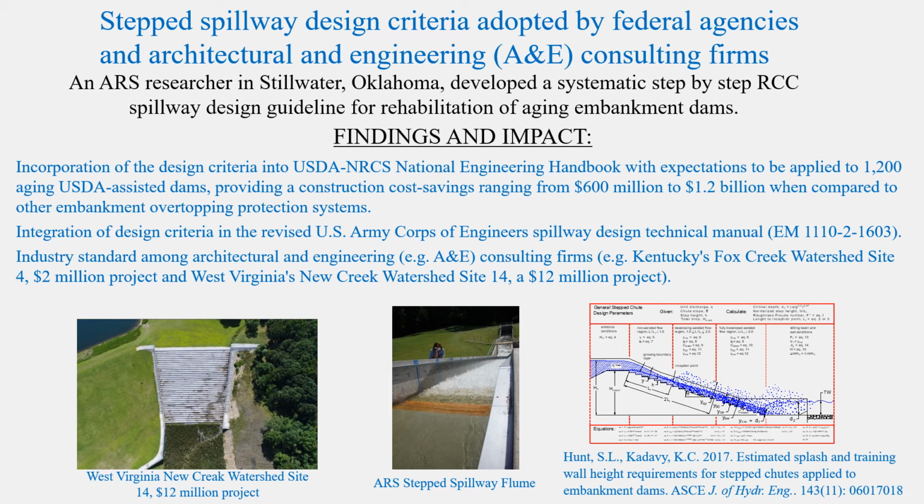The steps create significant energy dissipation compared to a smooth chute. Thus, you can have a smaller stilling basin footprint for step chutes than for smooth concrete chutes. The smooth chute requires reinforced concrete, which is more expensive than roller compacted concrete, and smooth chutes typically require a drainage system be installed underneath the concrete slab at additional cost.